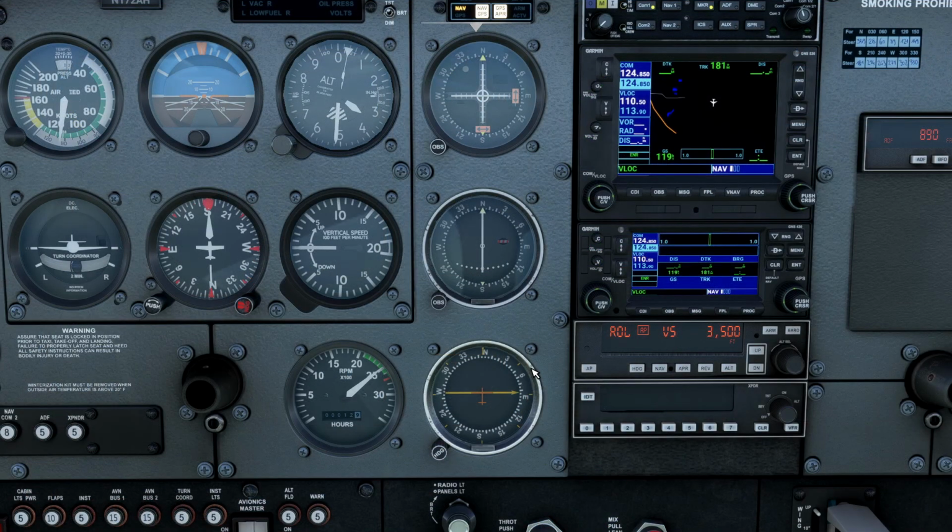Alright, so let's talk about the roll modes that are available to us on the autopilot. We've already talked about the wing leveler mode, so the next mode is the heading hold mode. We can engage that by pushing the heading mode select button. And we know we're in the heading hold mode by the roll mode display displaying HDG. And we can actually use the heading mode select button to toggle between the heading hold mode and the wing leveler. So each time we hit that, it'll toggle between those 2 modes.